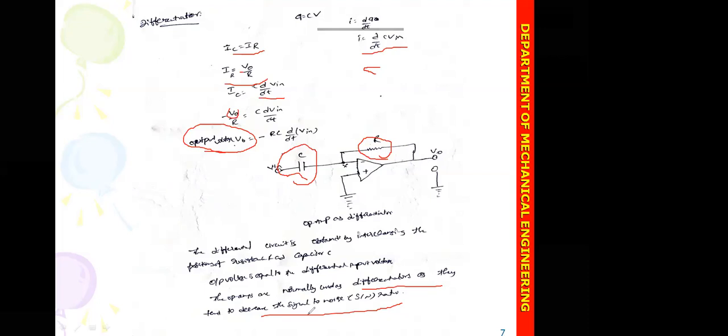So any questions from this? Here, in this circuit, it is arranged again, I'm repeating, the differentiator. R is the feedback resistor, arranged from the output to the inverting end, and a capacitor C is connected to the inverting end. The non-inverting end is ground, right?